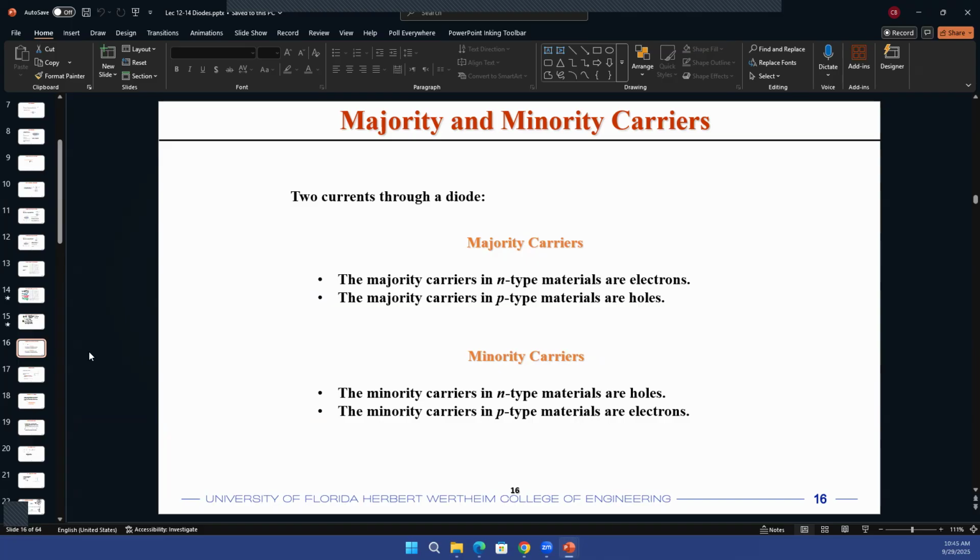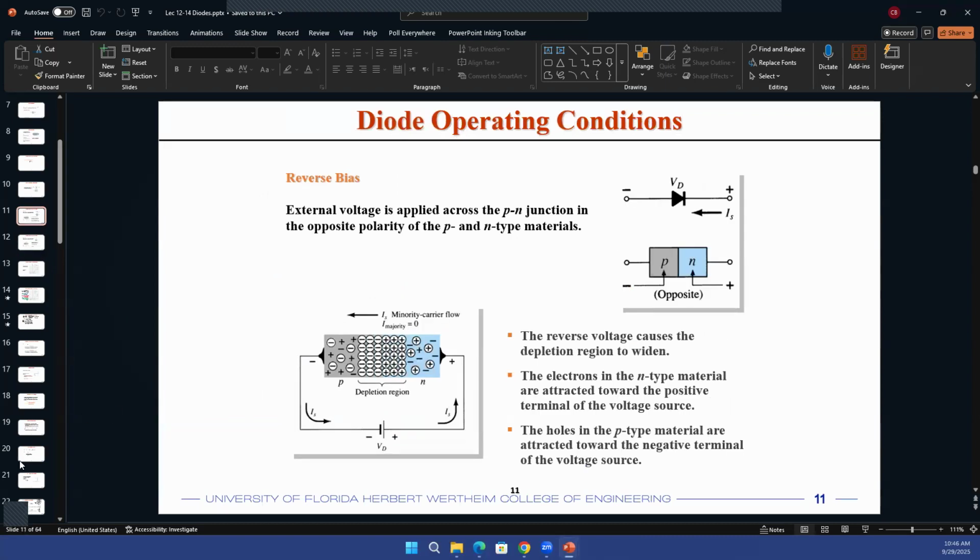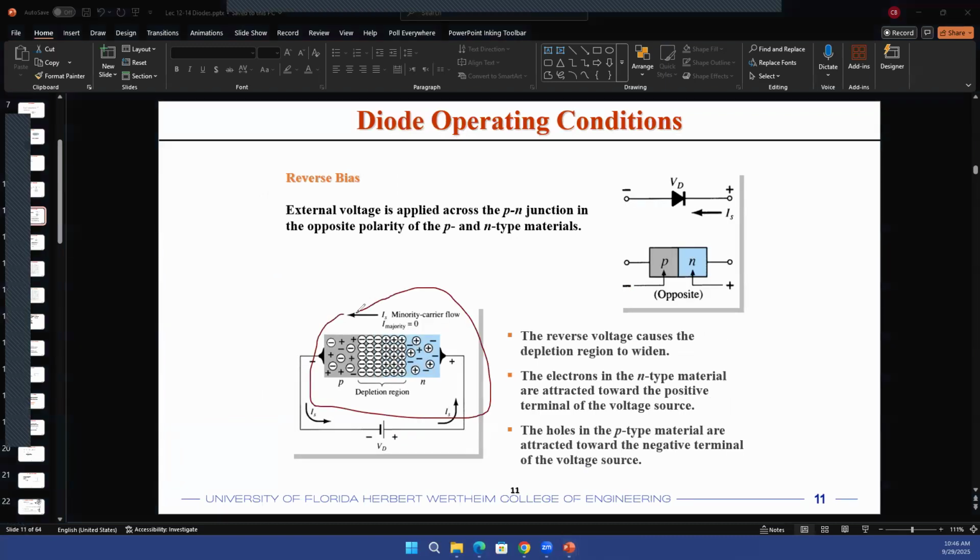So that's reverse biasing. And you know that in the reverse bias region, there will only be a small amount of leakage current. That's because there are minority carriers in the depletion region that you have for the diode. We have looked into the depletion region as well. If you look at this figure on the bottom left, if you have a reverse bias, then the width of the depletion region increases. And if you have a forward bias diode, the width of the depletion region decreases. It's kind of like how you have a bridge, and then part of that bridge is broken. So the electrons or the holes have to jump through that broken part of the bridge. If you have a reverse bias diode, the broken part is larger. If you have a forward bias diode, the broken part is smaller.